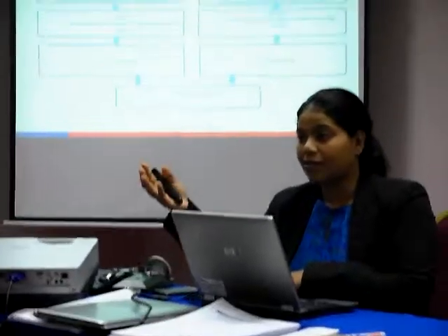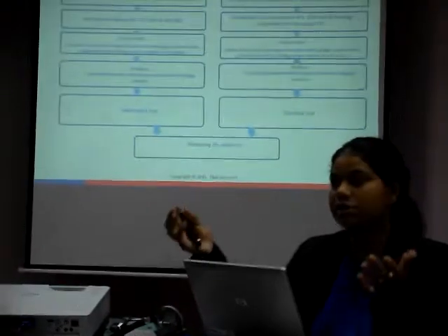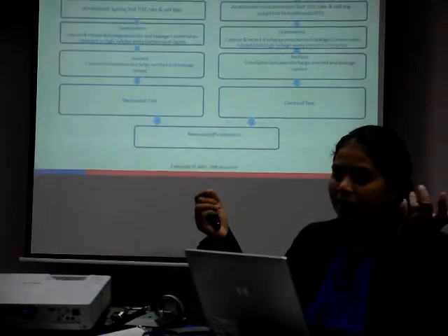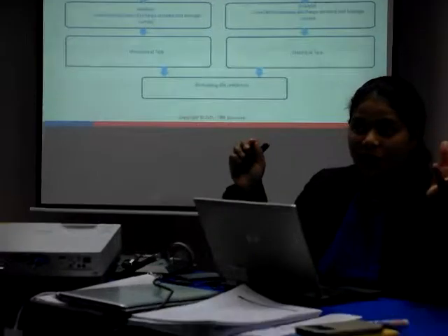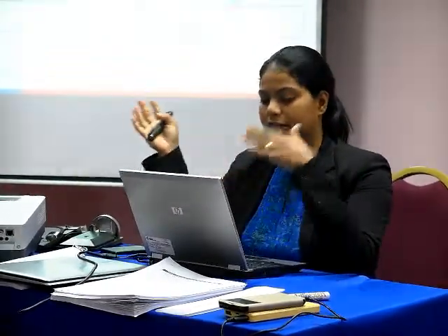The laboratory test, what do we have in mind so far? We want to perform accelerated aging, which consists of UV, rainfall, and salt fog. Why these three tests? Because in Malaysia, our weather, solar radiation, the intensity is quite high compared to other countries. And our rainfall, we have heavy rain. And salt fog at different areas. Salt fog towards the sea, the coastal area, is going to be different. So we will also differentiate groups of insulators.